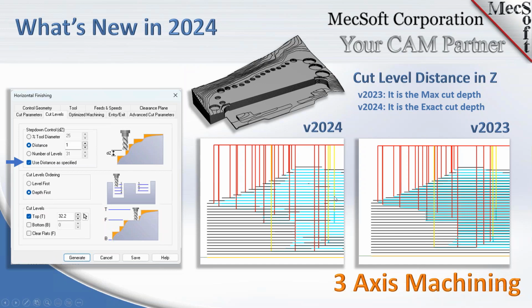Yeah, and also just look at these two images. The one on the right is in version 23, where the cut levels didn't fall exactly at the depth that the user specified, in this case a distance of 1 millimeter. If you look at this example part, it's a topographical stack of surfaces at 1 millimeter intervals. So now you can set the distance at 1 and check this box here, and it'll maintain exactly that distance, as you can see over here under the 2024 image.